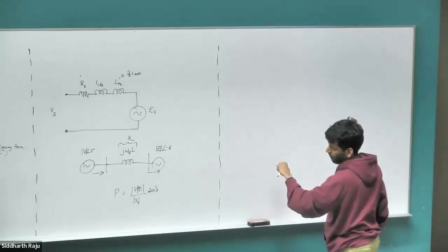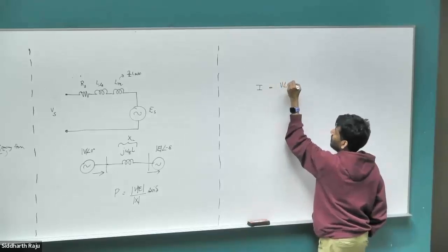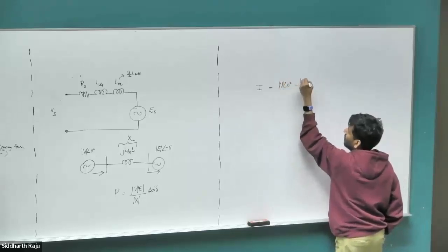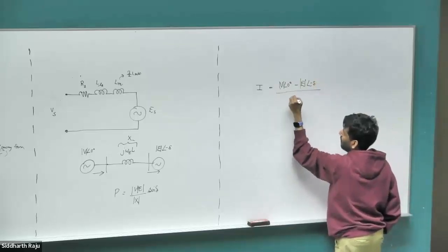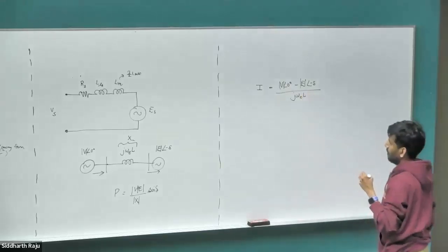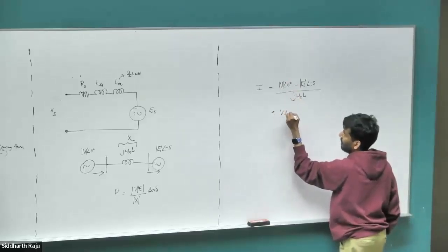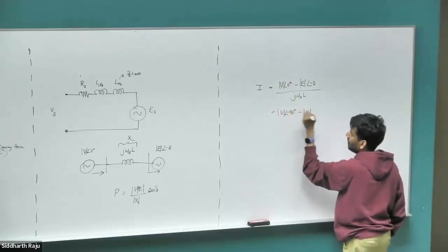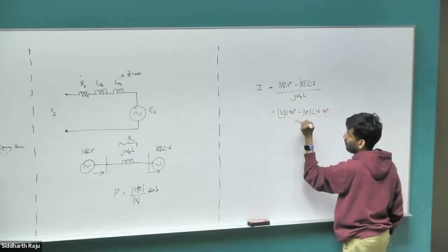So we have a voltage source, so the current through the reactance is going to be equal to V angle 0 degrees minus E angle negative delta, divided by j times omega L. Forget the absolute sign, just remember that it's always there, it represents the magnitude. If this j goes to the numerator, that would give in part a negative 90 degree angle, so the current is V angle negative 90 minus E angle negative delta minus 90 degrees, divided by omega L.